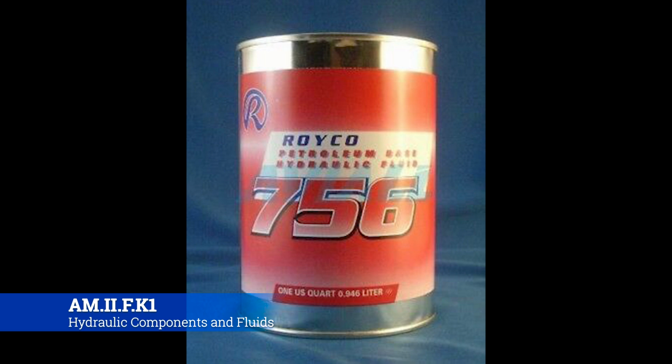It's processed from petroleum, so it's an oil byproduct that gets made. Thus, the classification, it's a mineral type of hydraulic fluid. Now, these have been around since the 40s. It's probably the oldest. It's the most widespread. Most of your general aviation aircraft, your smaller, like your single engine piston aircraft, are going to use 5606.